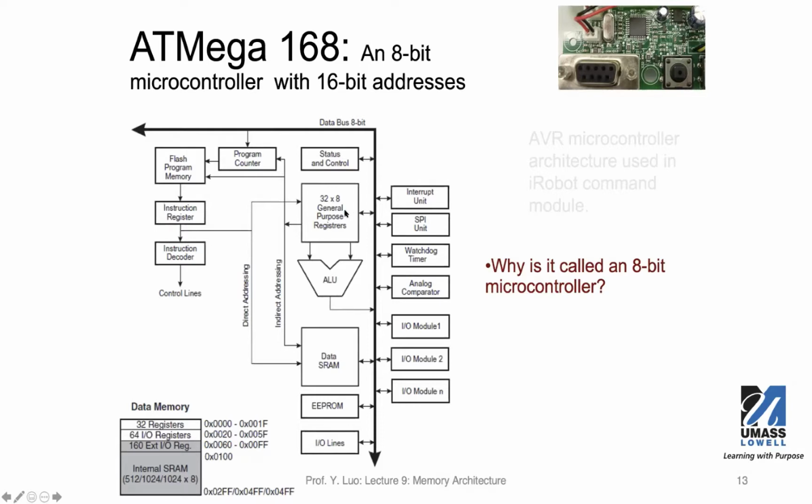So it connects the ALU with the memory, the data memory, also the EEPROM, and the program counter. And that connects to the program memory, which is based on flash. The instructions will be read from that program memory and decoded and then sent to the control so that the ALU can perform certain actions.